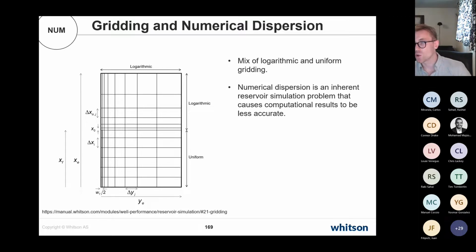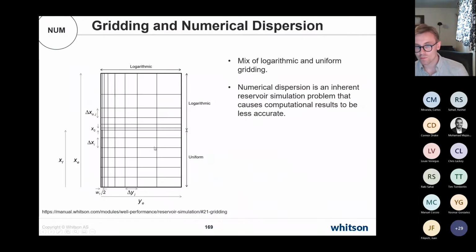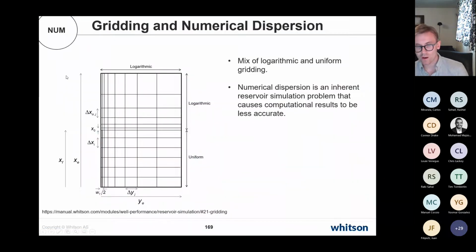We say that the results have not converged. But in most of these cases, we see that even our very low and low is capturing the most important physics in all cases. If you're unsure, you can just simply create a medium case, or test it with high. And if there are big differences there, which there should very seldom be, then you of course can use that instead.